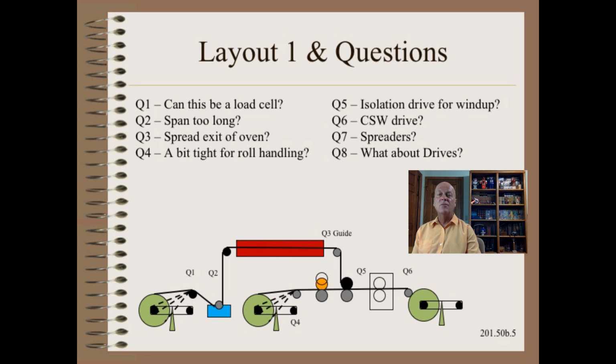If you look through these web handling related questions, you will note that not only do we have mechanical concerns, we also have controls concerns. Here we note that drives become more important at this stage. The drive engineer on your team should then also have had formal web handling training, so that they can advise on drive zones and control strategies appropriate for the properties of your new web products mix.